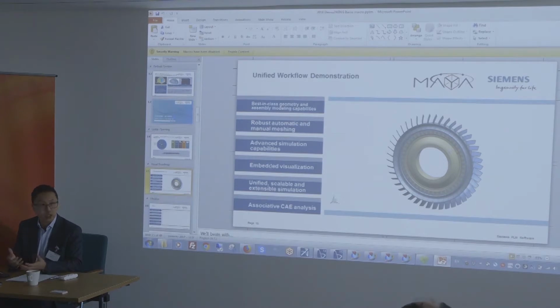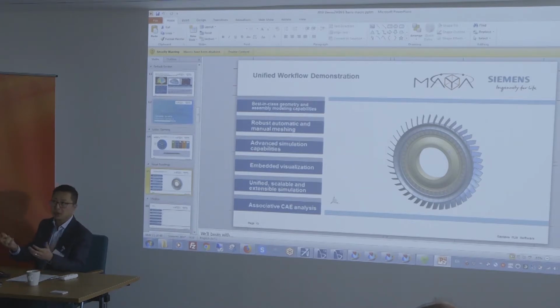automation. This is all the kind of things we can do in NX. Automate workflows or processes, and one of them is reverse engineering. So that could be done as well. So we'll see a typical problem we've found in the turbine industry where we want to get the cold geometry out of hot simulation. So we'll see how this can be done, and then we'll finish by doing non-negligible geometry change, like changing the curvature of a blade, for instance, which is typically not an easy feat to do, especially to keep that CAD associativity. So that's what I'll show.